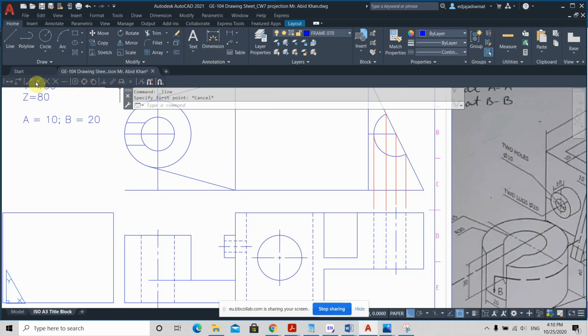If you click this, for example, I'm going to make a line, but many other object snaps appear. I don't like that. I can use the object snap toolbar to turn on only what you need temporarily. Once you're done, it will return back to normal. Like when I click this, no other object snap will appear. It will only be the endpoint object snap, because I click endpoint here in the object snap toolbar.